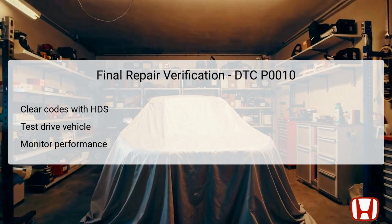Following this, it is advisable to perform a test drive to see how the engine responds under various operating conditions. Monitoring the engine performance during acceleration and idling will provide insight into the effectiveness of the repairs. If no codes reappear and performance is normal, it indicates that the initial DTC P0010 concern was indeed addressed properly, affirming the integrity of the repairs conducted.